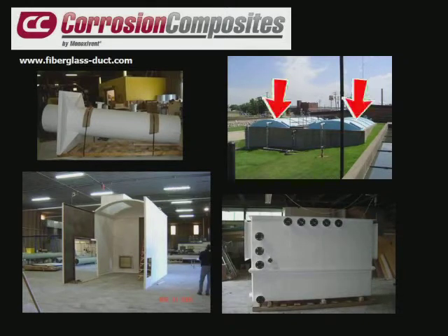In the upper right, we have some 20-foot span covers over wastewater tanks, barrel type covers that bolt together. We've done several projects like this. It's for odor control, and it also controls the foam that can build up in the wastewater tanks. That also has a core material, and it is a balsa core for stiffness to keep them light and stiff.